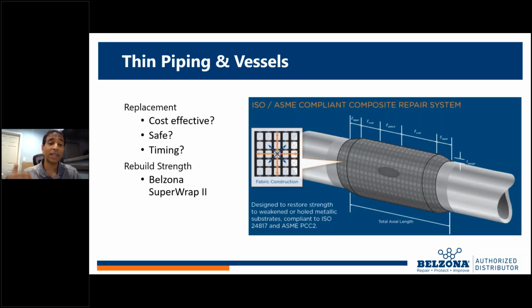Let's talk about already in process, active equipment. We talk about piping, we talk about vessels. In this case, our inspection team has gone out. They're doing their annual inspections, and they find that there are some areas of this equipment that are below their T minimum. That sends a flag. Hey, we've got a problem here. The engineer starts looking at it and they decide we've got to do something about this. Given our current corrosion rates, we might be in a position where we have a loss of primary containment. It could be unexpected. And so let's be preventative. Let's be proactive. Let's prevent the problem from happening.